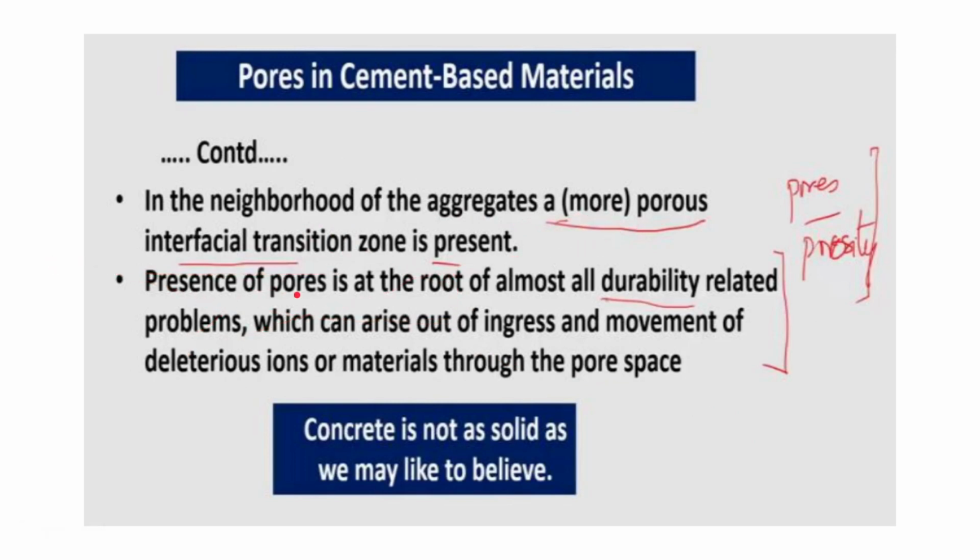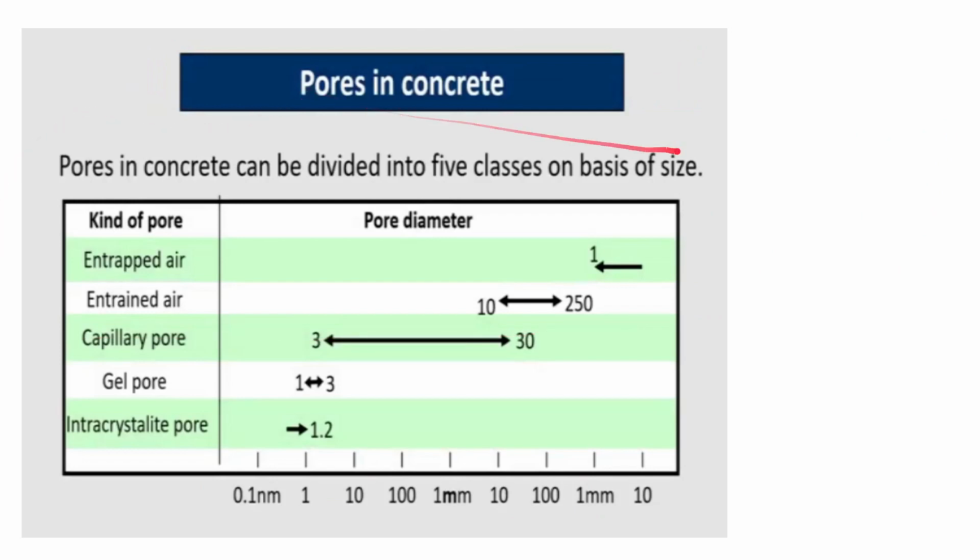Presence of pores is at the root of almost all durability related problems, which result in ingress and movement of deleterious ions or materials like the chloride ion through the pore space. So this makes us realize that concrete is not as solid as we think it is. In words we always say we need a concrete solution, but that concrete also has some pores. So, pores in concrete.